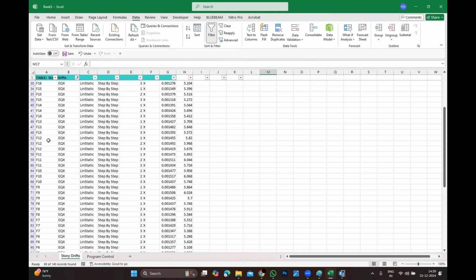A 9th floor, 10th floor mechanical floor load. The 10th floor will add a huge load, 15 kilonewtons per square meter, for the water tank. Say for example the chiller phase, the total mechanical floor is 15 kilonewtons per square meter live load. Run it.